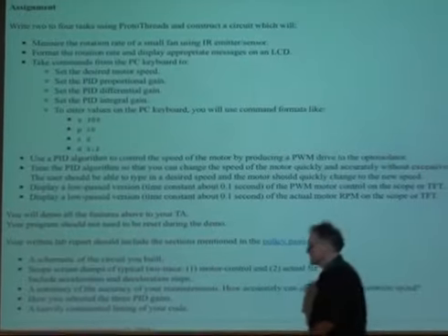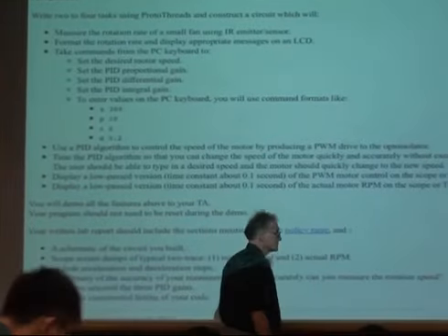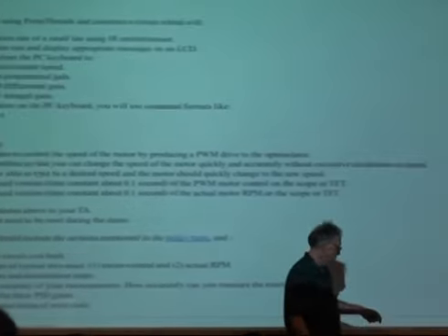So, for instance, you might put the oscilloscope on slow scan, maybe 500 milliseconds per division. You have one person ready to start and stop the oscilloscope trace, and the other person poised at the keyboard to change the speed commands.